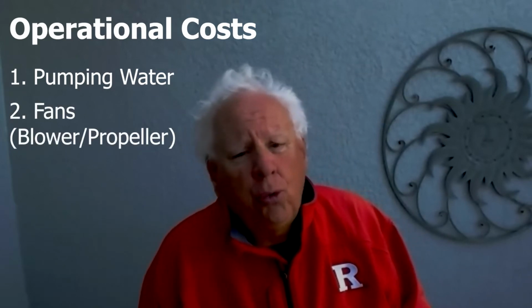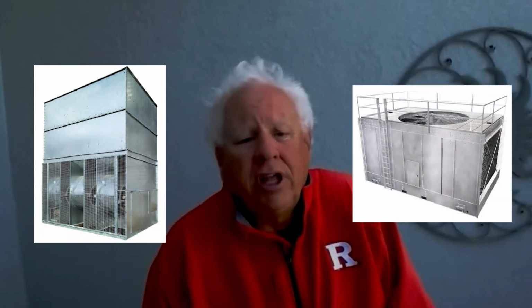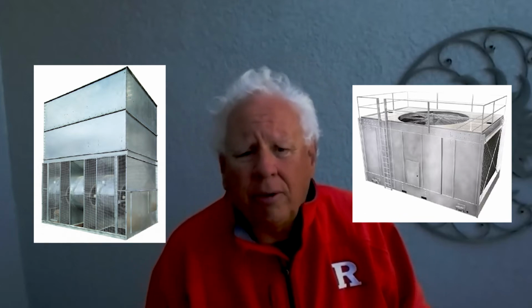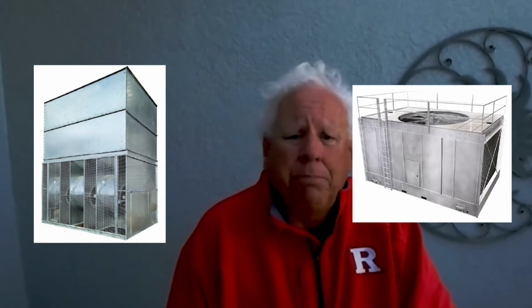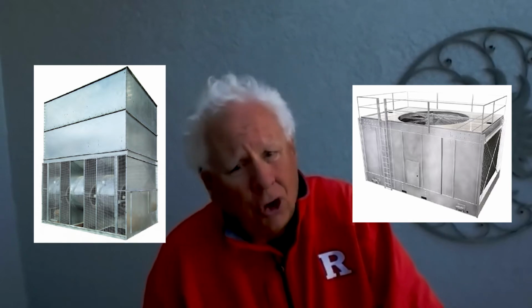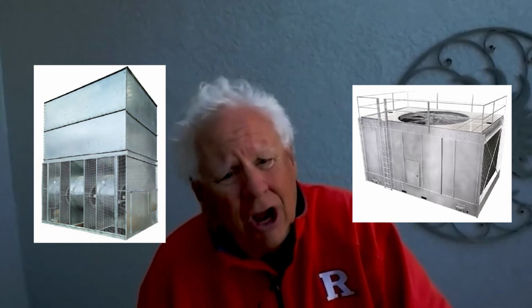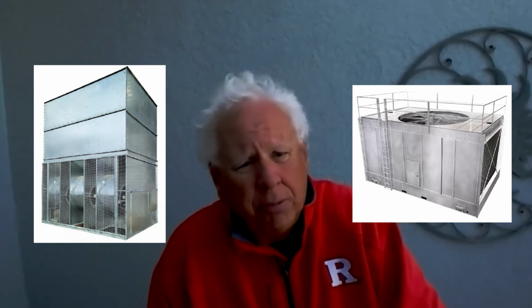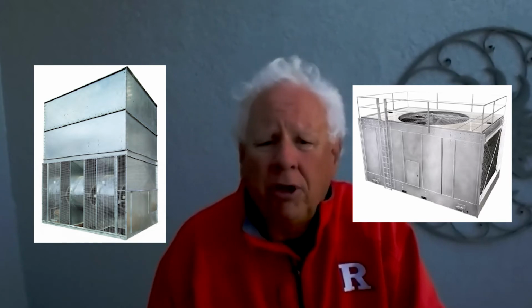Air is moved through two main ways. The first is a blower. It's pushing. It's a positive flow. And the other is a propeller type, where you're essentially going to put a propeller on the top of the cooling tower and suck air into the system. Turns out that if you're looking at blowers versus propeller systems, the cost of your fans is going to be significantly higher for blowers, and therefore the benefits from making adjustments or doing energy efficiency projects on the fan system become much more relevant.